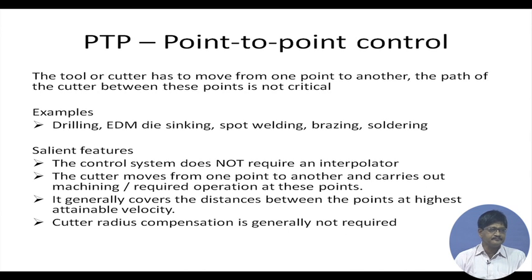So, first of all, let us take up the discussion on point-to-point control. What is point-to-point control? Whenever we are talking of machine tools, there are some machine tools in which the required operation is only at some definite points, and the cutter simply has to reach those points and carry out the operation. The path taken by the cutter between these points is not critical. That means it is not very important.